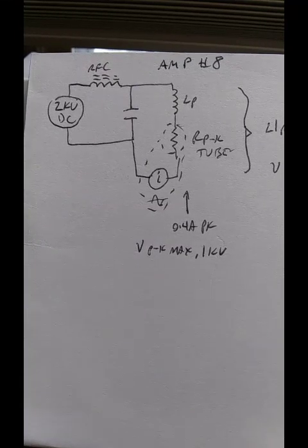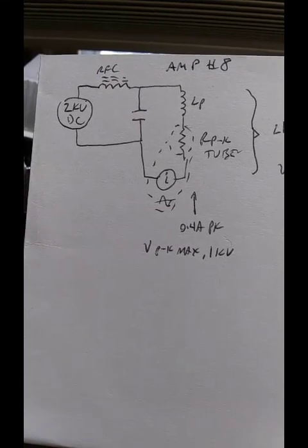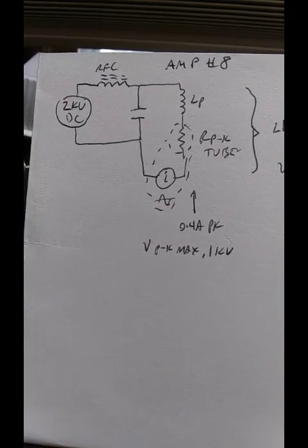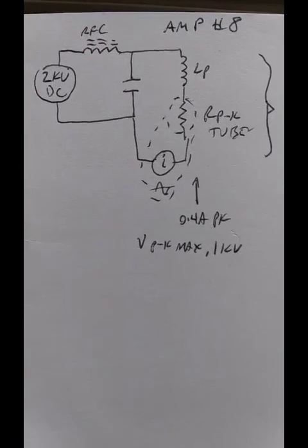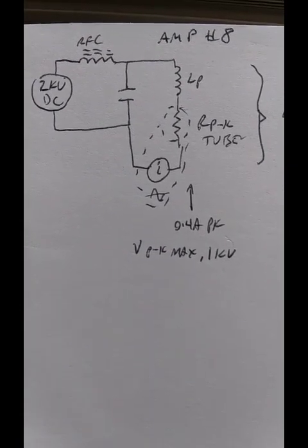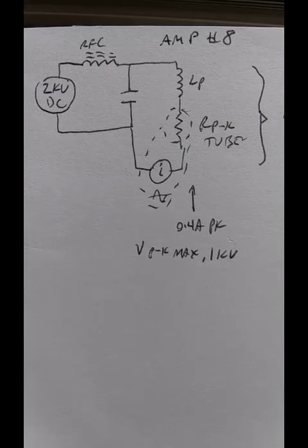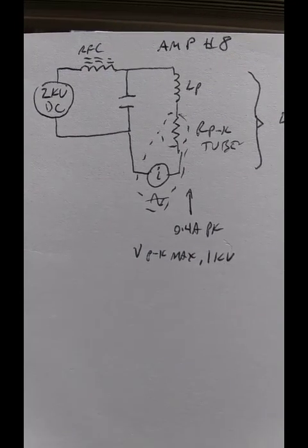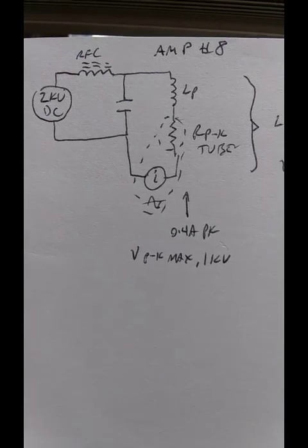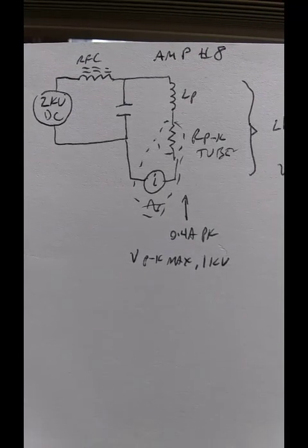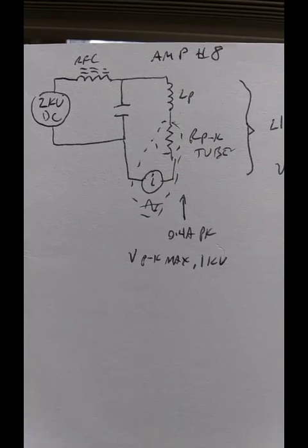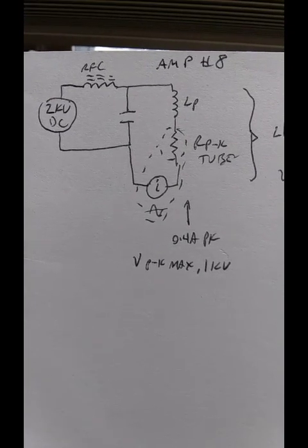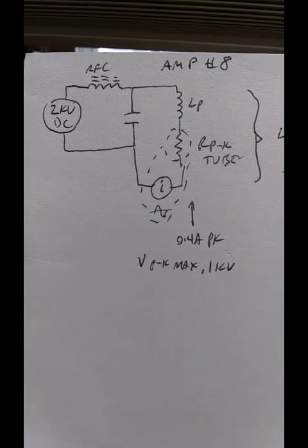With the tube being a constant resistance, there must be a varying current or the circuit does nothing. And this is where the convention of a tube being a current source comes from, and the current source is shown at the bottom, the ACI in a circle with a sine wave below it. That's in series with the plate to cathode resistance. Critical to note that the tube does not cause voltage change on the plate.